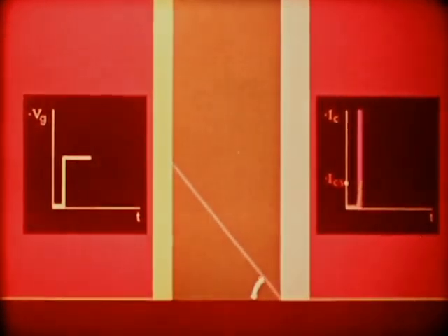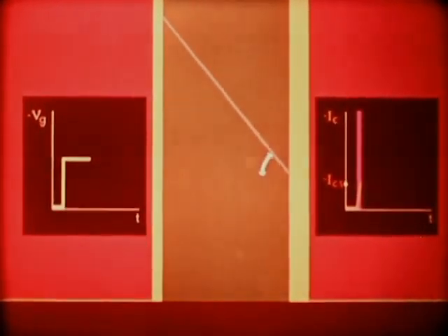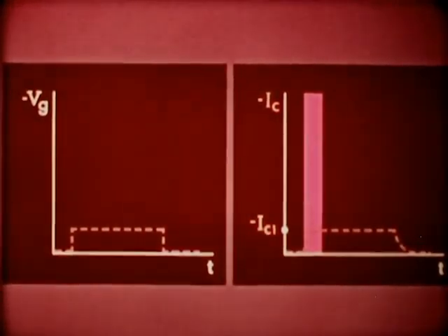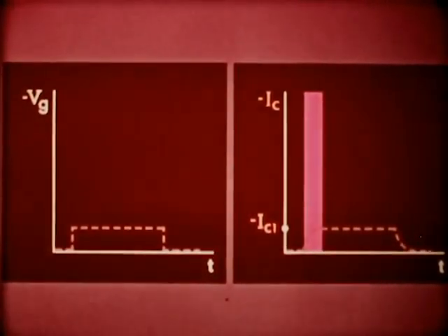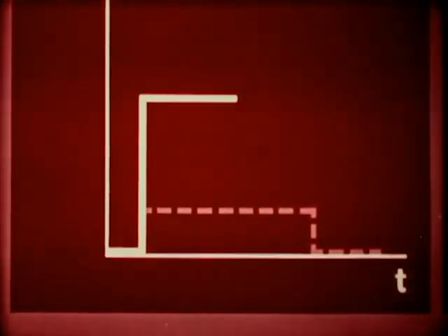The whole concentration curve rises still further until the number of recombinations per second becomes equal to the base current, which is, of course, the input current. If, however, the transistor had not reached this saturation state, the collector current would have attained a much higher value. So in order to reduce the time taken for the current to become stable, it is necessary that the transistor be brought rapidly into saturation. In the same way, we can expect that TF can be reduced by bringing the transistor rapidly into cutoff.